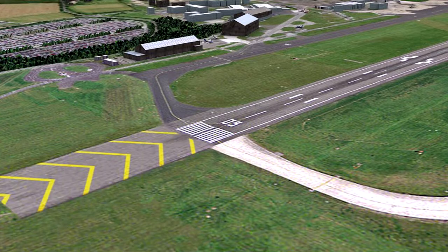A stopway is the defined rectangular area beyond the end of the TORA in the direction of takeoff, no less wide than the runway and centered upon the extended centerline of the runway, able to support the aeroplane during an aborted takeoff without causing structural damage to the aeroplane, and designated by the airport authorities for use in decelerating the aeroplane during an aborted takeoff.